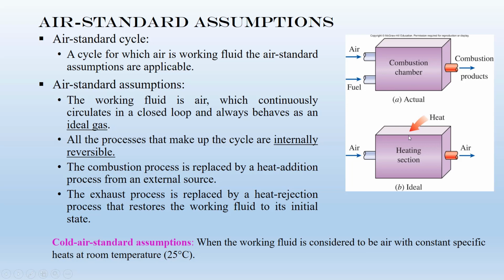The first thing is that we assume that the working fluid is air. We cancel the fuel, correct? The second one, we assume that this air actually is an ideal gas, meaning that you can use the ideal gas equation of state to calculate the property of this air.